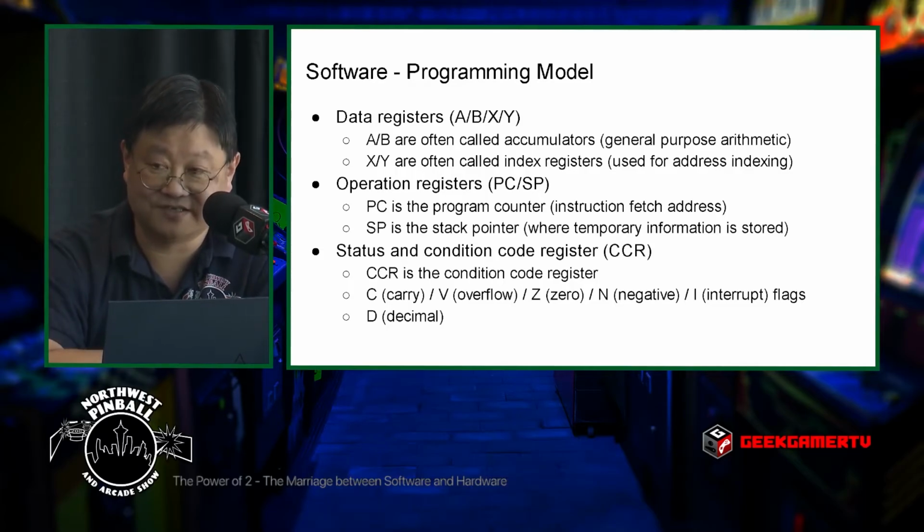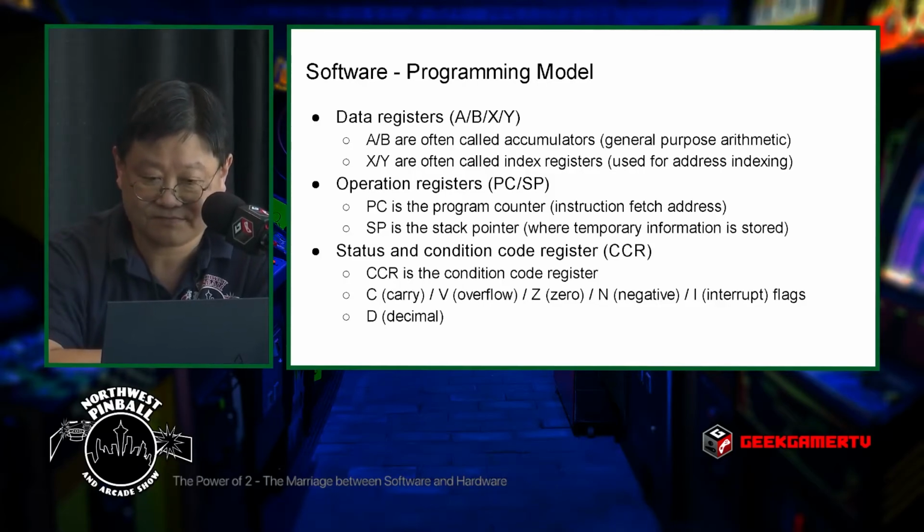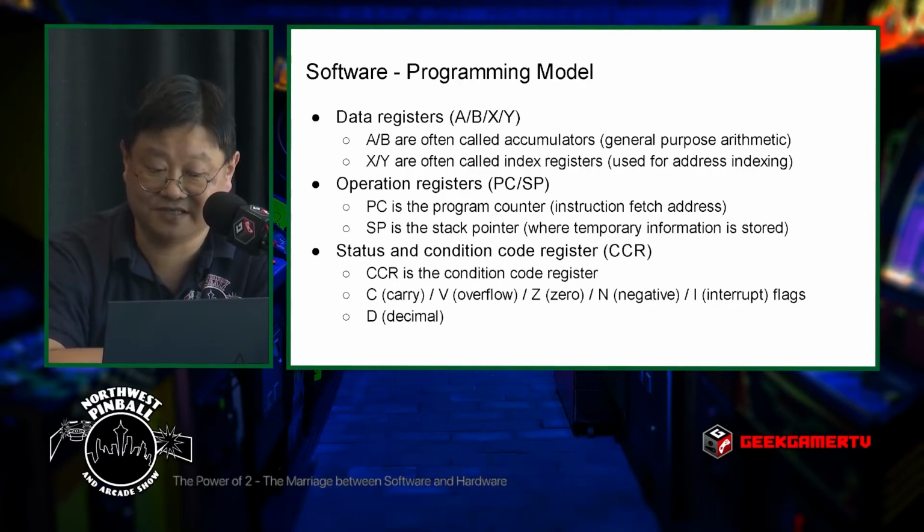The X and Y registers are index registers, and in the 6502 world, those are 8-bit, and in the 6809 world, those are 16-bit. And I think there's only 1 register in the 6809, the X register. They're used for addressing indexing. There are special operation registers, 16 bits wide, that the processor uses, the program counter, the PC, and the stack pointer, where stuff is placed onto the stack.